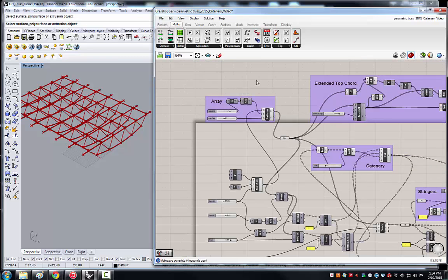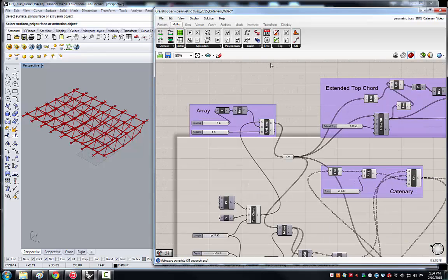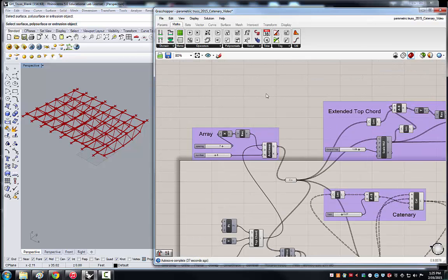We're going to now add the rotation function so that you can see, starting from the first truss as a level horizontal element, adding an incremental rotation of a number of degrees as we go. That will be useful for you to make even a simple kind of curving or sweeping roof. There are other ways that you can induce curvature to this, perhaps by importing geometry and arraying along a curve, etc. But here we're building everything from scratch with no input geometry.